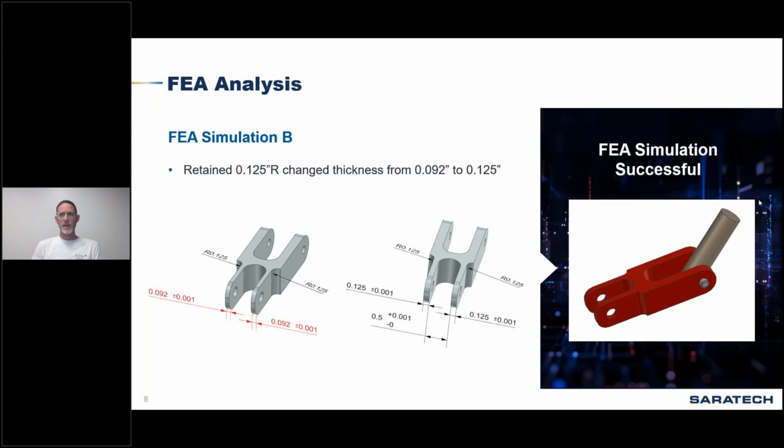In essence, if I have titanium material, my parts go from this big to this big, and my stock is a basic shape. I can just make an instance of a roughing strategy that goes from stock to near net and apply it to every single part just by clicking on something and dragging it onto the screen. So it's highly customized and highly templatized. We can process parts very quickly and very accurately.